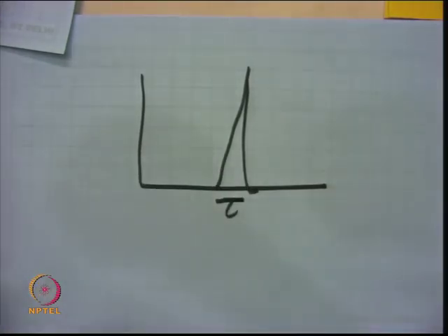If you inject a dye along with some water, then under plug flow condition, the dye should come at the same time, just like a solid ball. But this does not happen. If you put some KMnO4, it will disperse, it will diffuse, depending upon the superficial velocity. So, there are two terms basically when you talk about flow. Flow is because of two terms contributing.